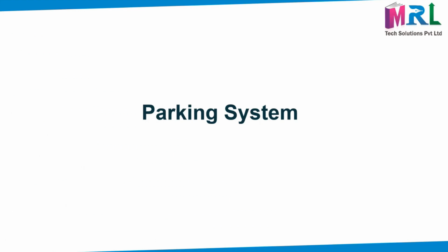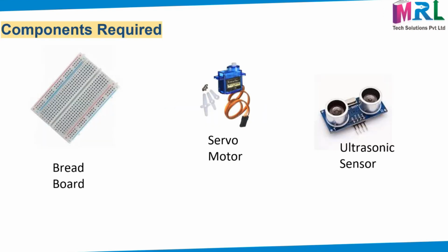So we are going to build an automatic parking system. There is no need for any security force to check whether the space is empty or not. All those things are done automatically using this ESP32 board. The components needed are a breadboard, servo motor, ultrasonic sensor, and the ESP32.